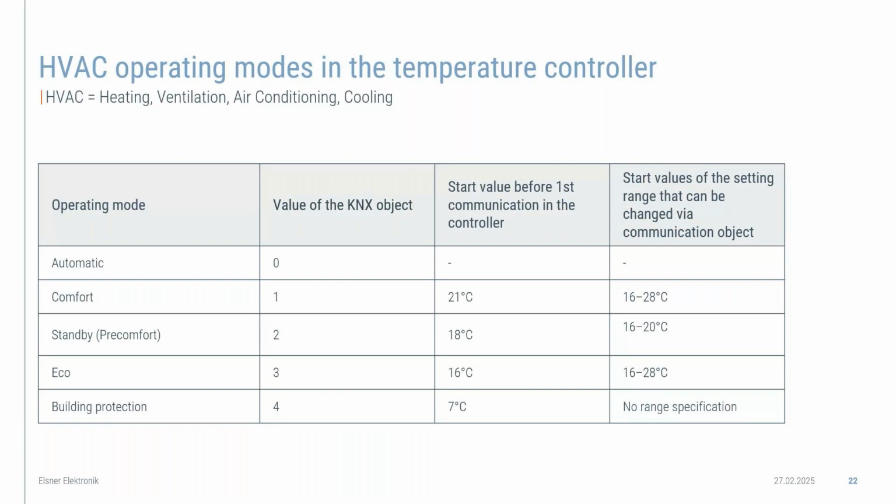That's probably old news for the KNX professional amongst our listeners today. This HVAC switchover can be used, for example, to lower the temperature on the controller display when a room is not in use. It is conceivable to lower the room temperature depending on the time, period, calendar, or for example, to lower the heating during school vacations.